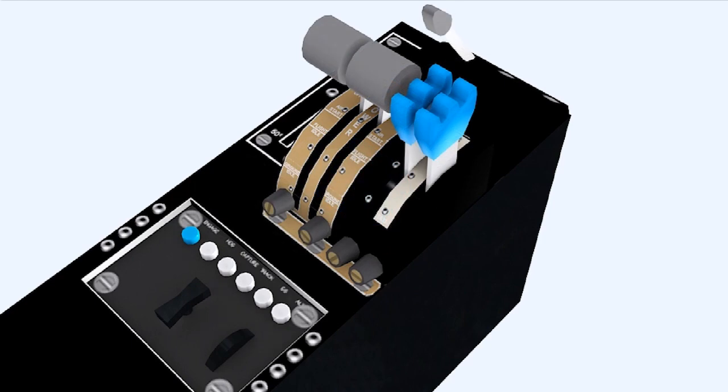As power is applied for takeoff, the flight fine pitch stop lever is forced into the flight position by the action of moving the power levers to the takeoff power position. The FFPS light and/or beta lights are extinguished.